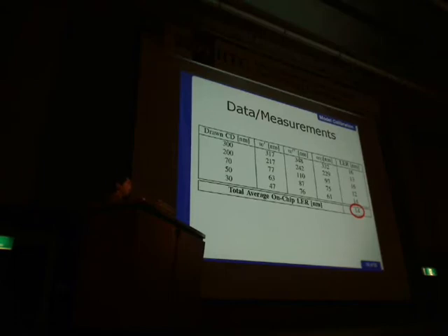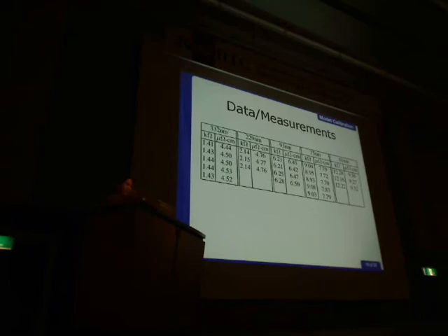These are the drawn dimensions. Obviously, with even lithography, forward scattering and back scattering, you have a biasing that occurs. If I was trying to draw a 300 nanometer line, it would have roughly a 30 nanometer bias added to it. Then I extracted what this undulation, this net amplitude of LER, was. So we first have 14. And then here are the data measurements.